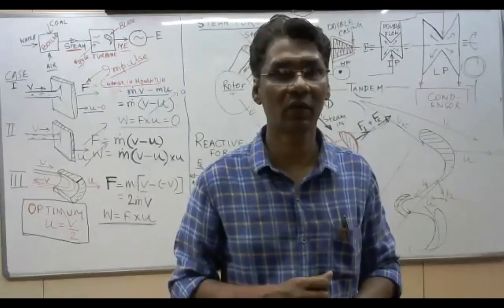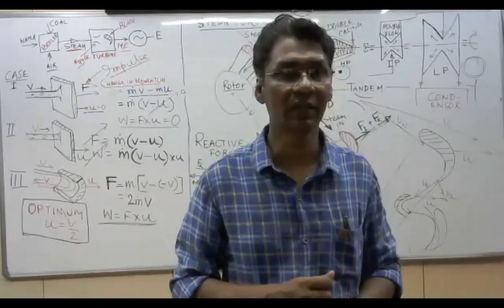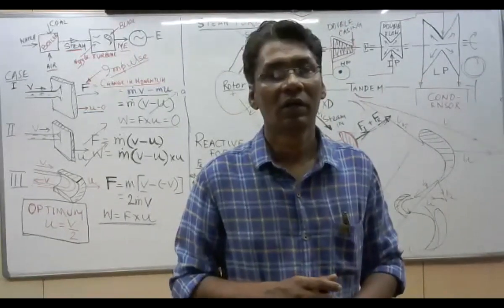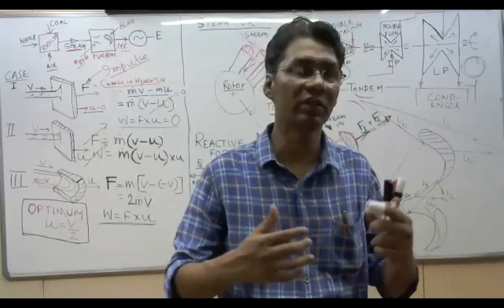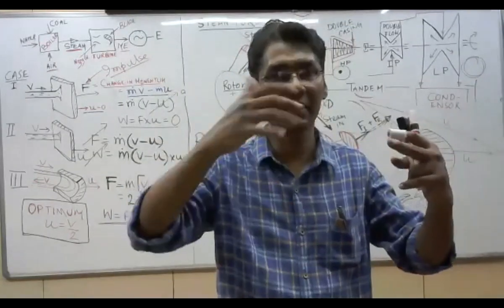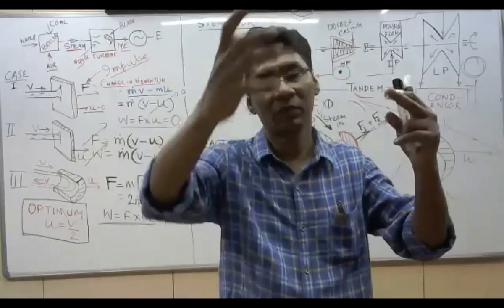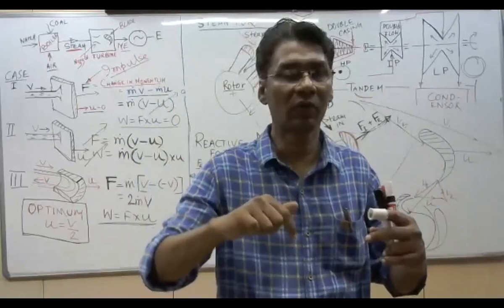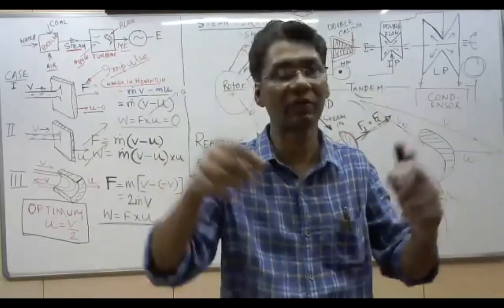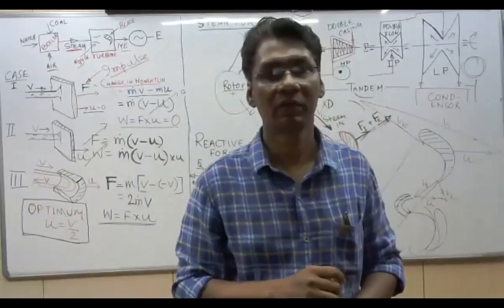Why are there holes in the rotor? In a turbine, if the rotor has holes, they are called balancing holes. If steam is there, it is a balancing hole. Uniform pressure will be distributed across the turbine rotor. If the holes are in the blade, that is for lacing wire.